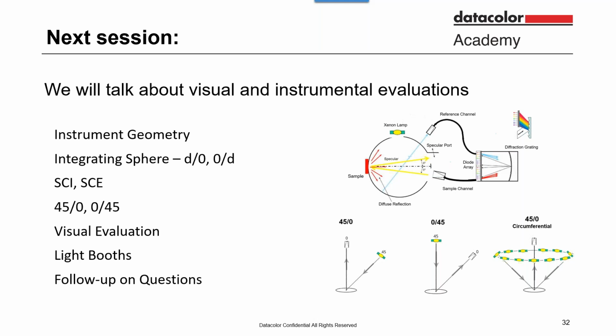But if there are changes going on in the process, or something else going on there, it's hard to come up with a tolerance to compensate for it. For example, if we know that a process is making something lighter or darker, and that's a real variable, like a printing press where lightness and darkness varies a lot from run to run, you would say that the tolerance in delta L has to always be greater.